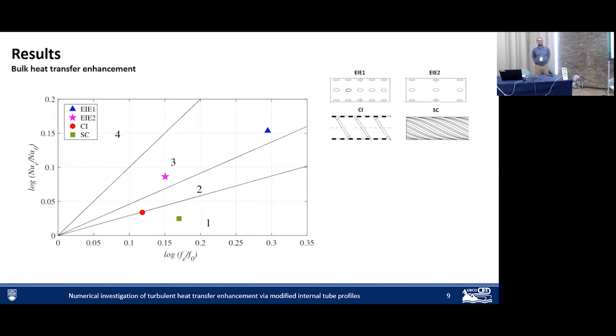One more. I was wondering, these elements can be seen somehow as roughness, right? Yes. In a way, did you see in what regime you are in terms of the roughness? Yes, these would be big roughness elements. Their height in terms of y plus for all of them is 100. So they stick out well beyond the viscous sublayer, actually beyond the overlap region, into the log-law region.